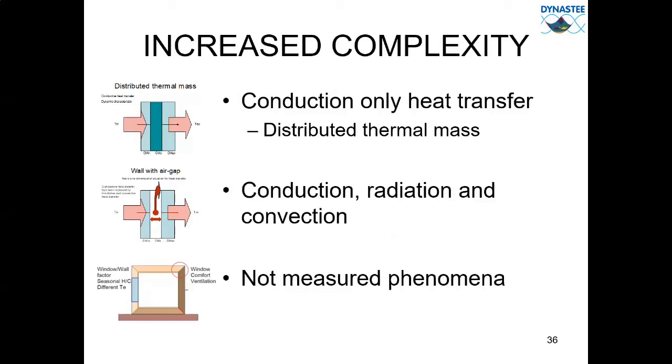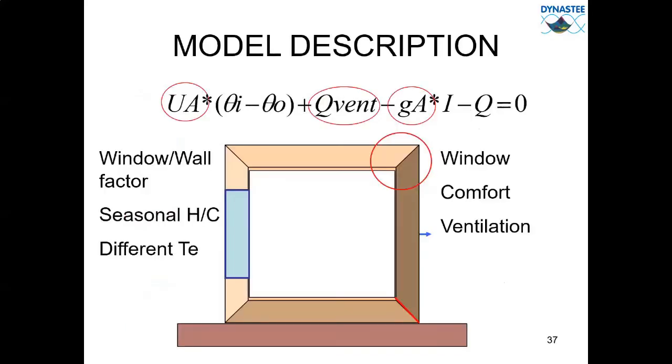So this three-story building may become a one-zone object in its first simplification. It has to deal with different ambient temperatures, as well as different wall compositions, including windows or no windows. Corner effects may take place, as well as stratification in the space, in the volume. And of course, the impact of solar radiation through the windows. That might give a seasonal impact.